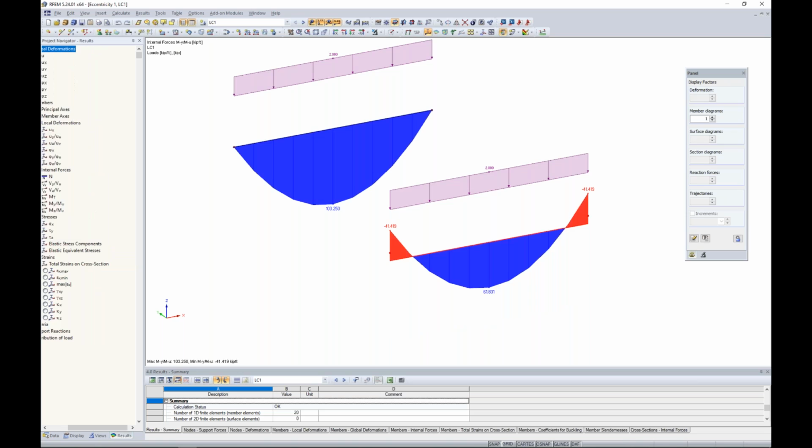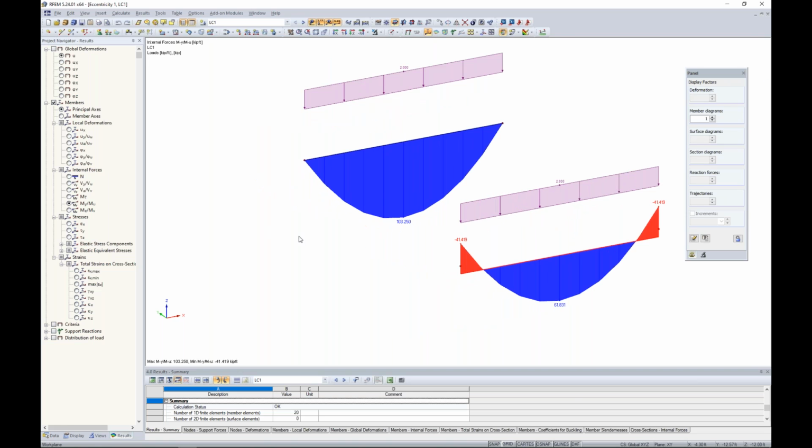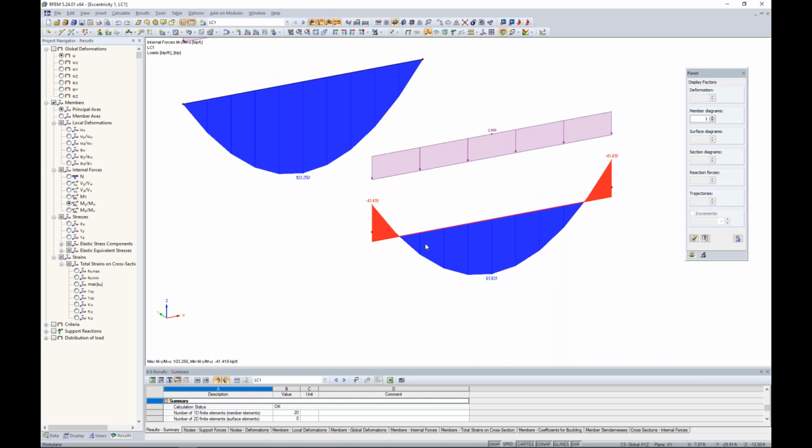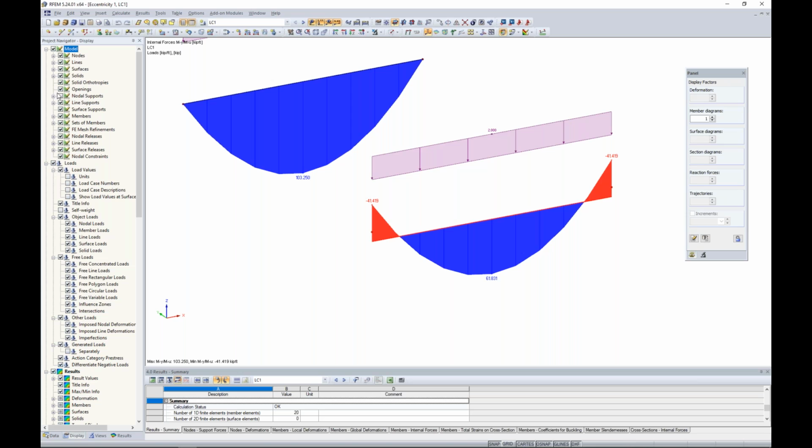We'll immediately start off with the moment diagram. So, a simply supported beam: we take a look at our first example here. This is exactly as we'd expect for our moment diagram, peak moment right here at the center. But as we transition into those nodal supports, which are a pin-roller type situation, we expect no moment. Well, by introducing this eccentricity here to drop the top of steel down to where our nodal support is, we now have a negative bending moment here due to those rigid elements at the end. Our peak moment here in the center is almost half of what we're seeing with our original beam element.